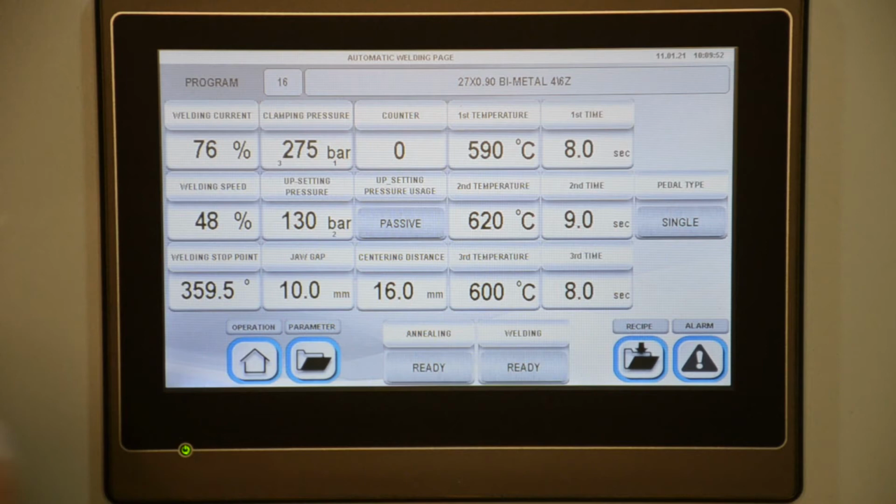You can clamp your blade into the jaws to make only the annealing operation and press the start button. In this operation, you will need to adjust the parallel clamping of the jaws when you do a size change. This is the only operation on the machine which must be adjusted manually.